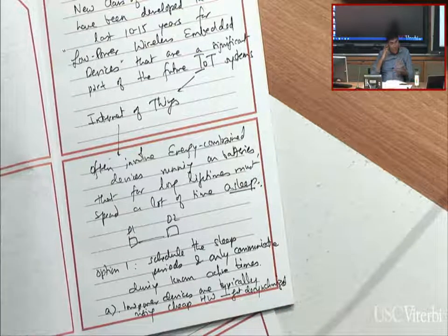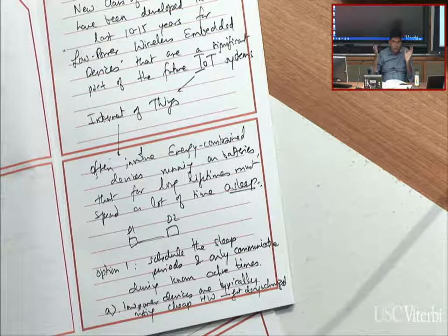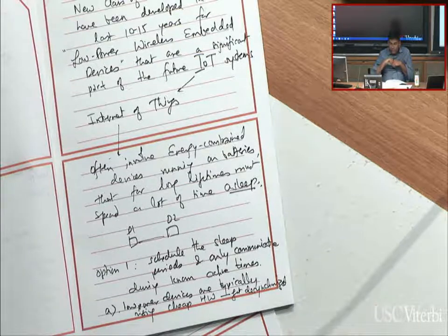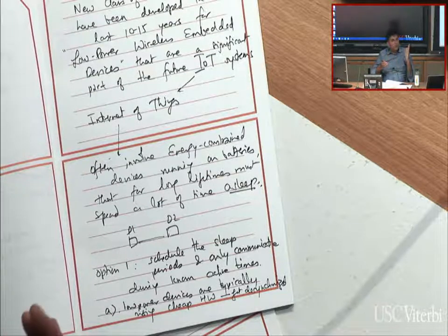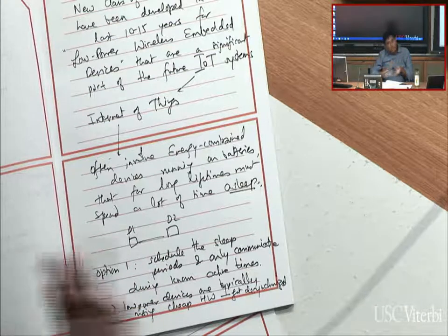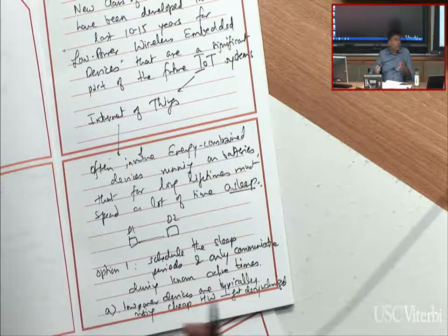What I mean by that is that you might tell them, okay, he's going to wake up in a few seconds from now, and it's going to keep doing that. So you tell these nodes, wake up every 3 seconds, and then you can communicate. But if your clock is running faster or slower than the clock of the other device, you might both initially wake up every 3 seconds, but over time the clocks start to drift apart. One of them is moving a little bit faster than the other. It wakes up a little bit sooner and sooner and sooner. Pretty soon they go out of sync from each other. So this one wakes up, the other one's asleep. The other one wakes up, this one's asleep. So they will lose the synchronization that you built in and will no longer be able to communicate.